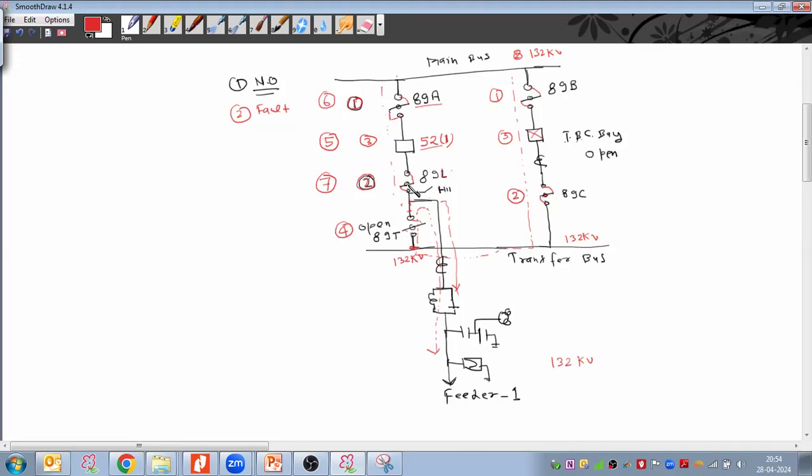Actually, this isolator was initially in the closed position, right? Yes, sir, it was not in the open position. Current was flowing through this earlier. So if you are opening the circuit breaker now, you get an open circuit inside the circuit breaker, right? And now you are not closing the isolators, you are opening their contacts, not attempting to close the circuit.